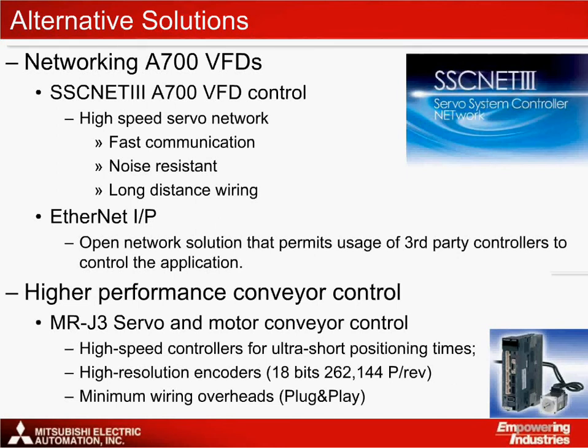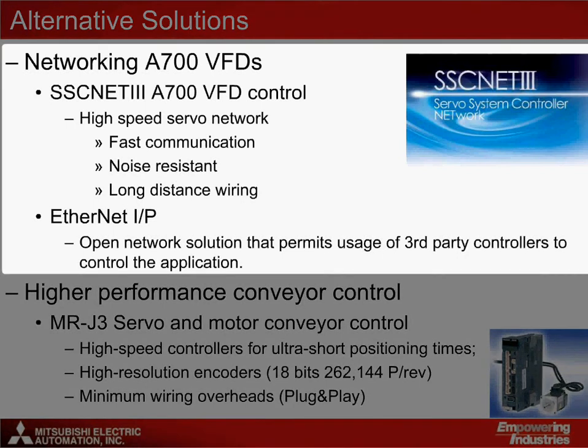SSCnet3 is Mitsubishi's closed network solution for communicating with servos. However, it also features an option to connect to the A700 drives. SSCnet3 uses an optical network that is not susceptible to background noise that can affect analog control.